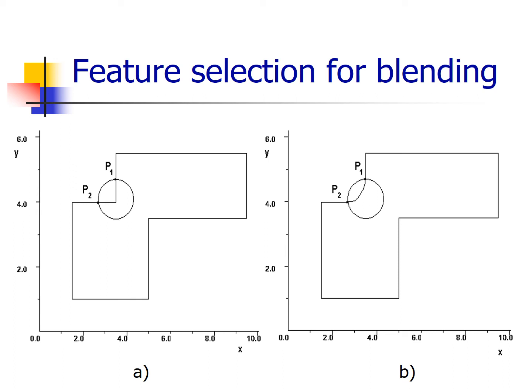A two-dimensional disk is used as a solid bounding the blend in the area near a single vertex, figure A. The pure union operation is replaced by the bounded blending. The expected bounded blend appears inside the bounding disk in the upper left part of the shape, in figure B. However, in comparison with bounded blending using control points, no blending appears in the lower right part of the shape. This example illustrates the local character of the blending with a bounding solid.